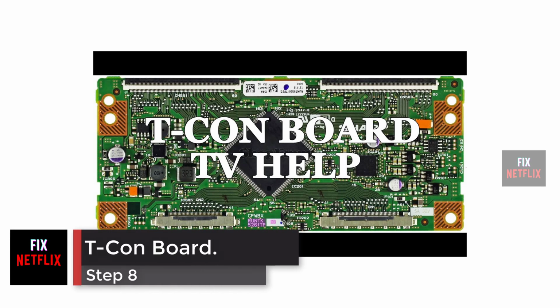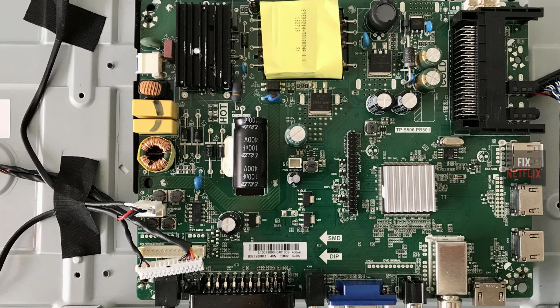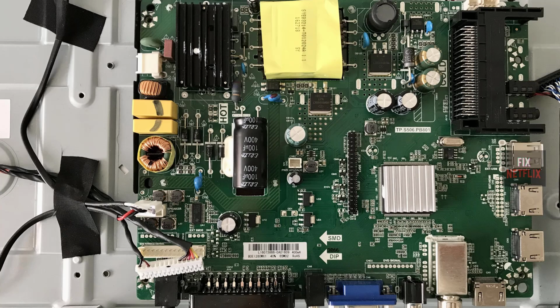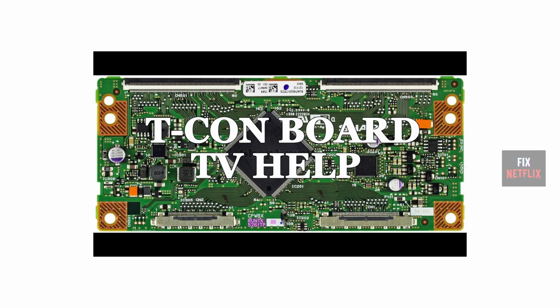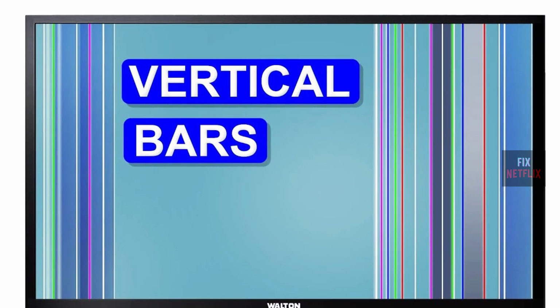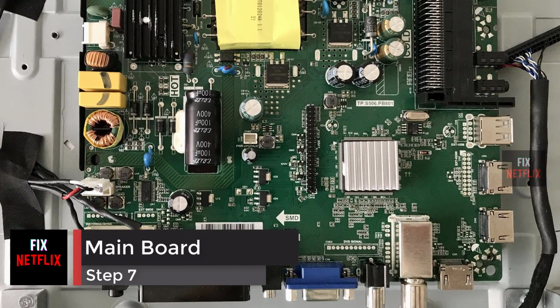Step 6. T-con board. This check for the T-con board also touches on the condition of the main board. Note that problems that show up on half of the screen, like bars or such, point to a failed main board, as T-con board errors show up on the whole screen. As an example, if an error like bars on the screen is on the whole screen, it is likely the T-con board.